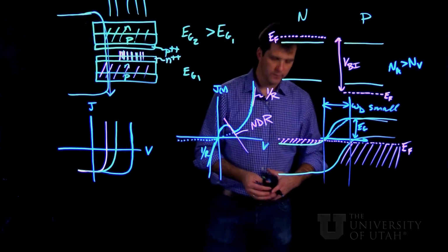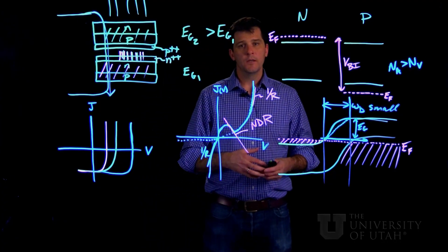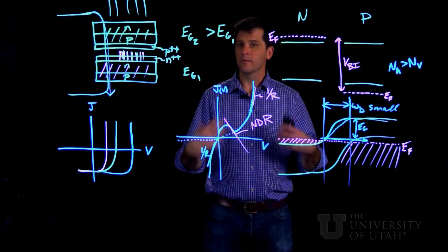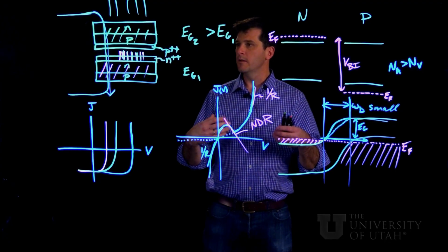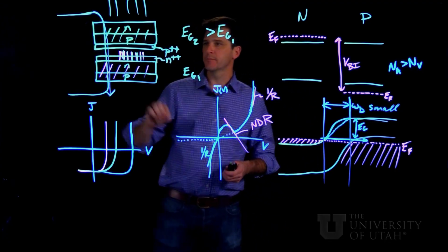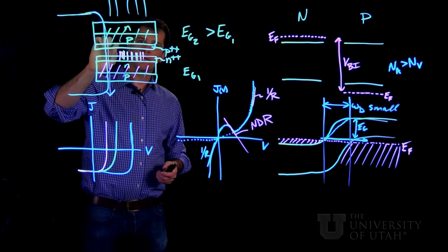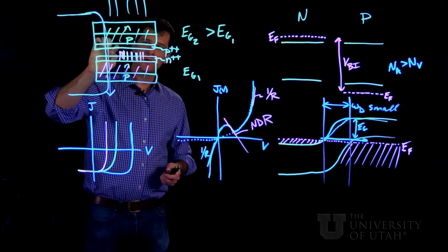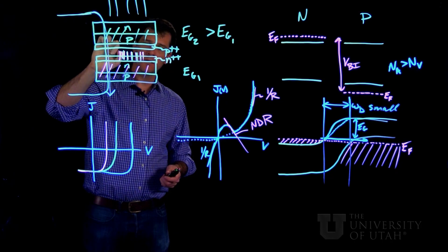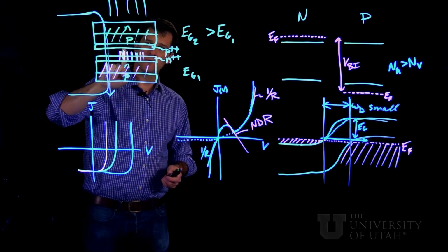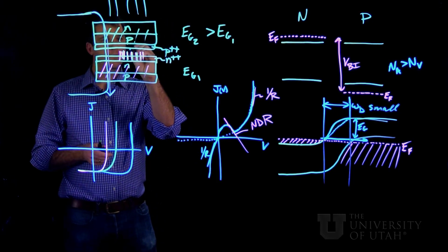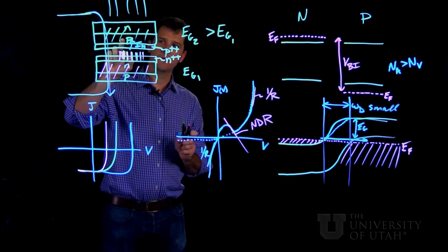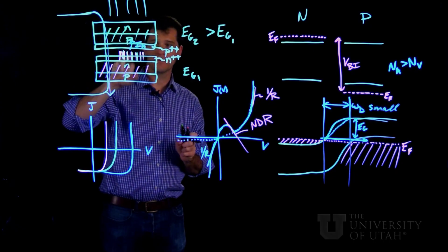The last thing to mention about a tunnel junction is that it, just like a PN junction, serves also sort of as a transformer of carrier type. So if we look here, our current is carried out of this solar cell by holes which are going in this direction into the p-type material to recombine with the minority electrons.